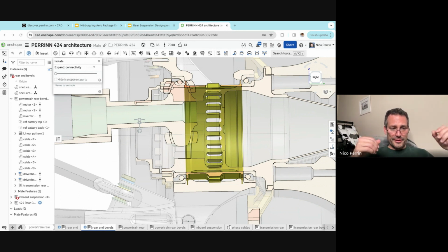Oh, and the cooling system as well. So the radiators and the pump and the pipes. And then there's the electrical system, but the high voltage will come with the motor and the inverter and the battery. But there will be some design for the low voltage, but that comes more at a drawing level for harnesses and things like that. So yeah, there is a lot to do.